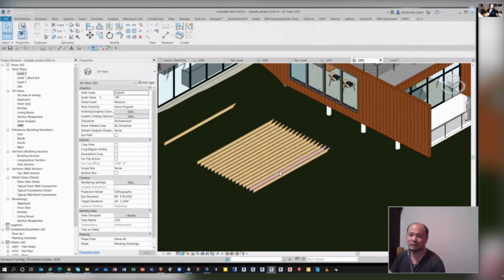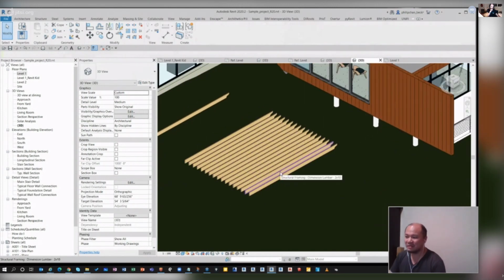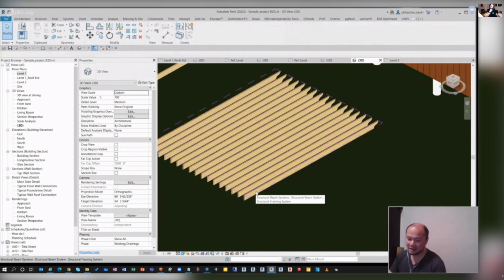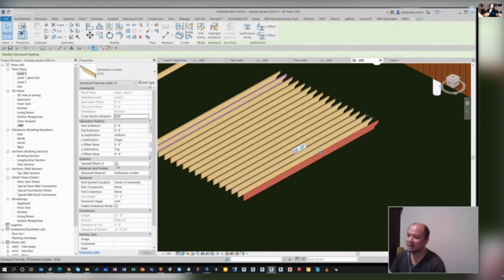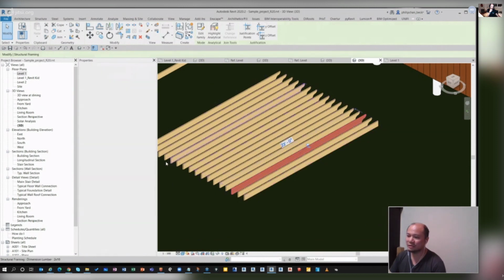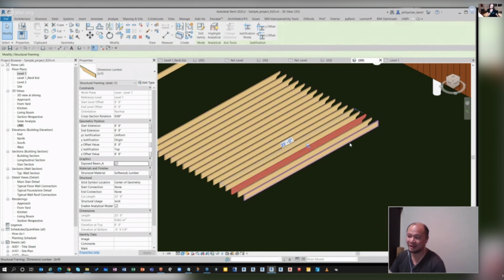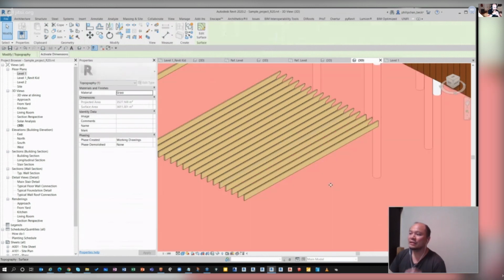I could use it for my exposed canopy, roof structure, what have you. Okay, so the cool part, of course, is I can tab select each beam again, and I can tell it to independently control some, maybe have exposed beam, maybe I have exposed beam at the end conditions, or vice versa, but I can totally do it now. The reason why I would start out with this existing structural beam framing family is that the only time you can use the beam system is to use the structural framing family using that specific template. So therefore, I don't want to use anything but that particular structural beam family. That's why using the one from out of the box is ideal.